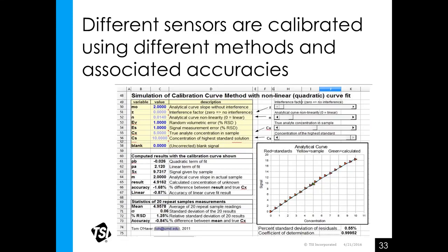So don't be afraid of the data. It's showing what's supposed to be there. That 0.999, that's a pretty good fit. Anything above 0.90 is good. This is an almost perfect fit for the data. So I would have good faith in this sensor that it's working properly, especially for a critical HVAC application.